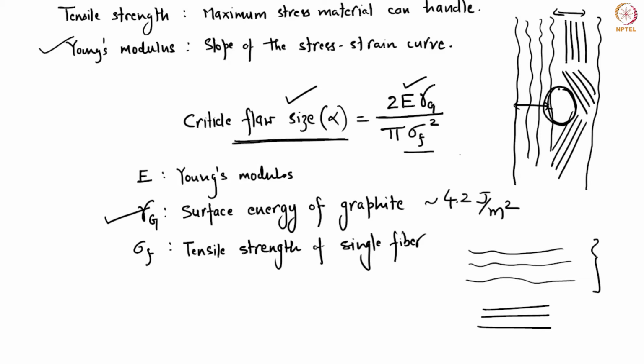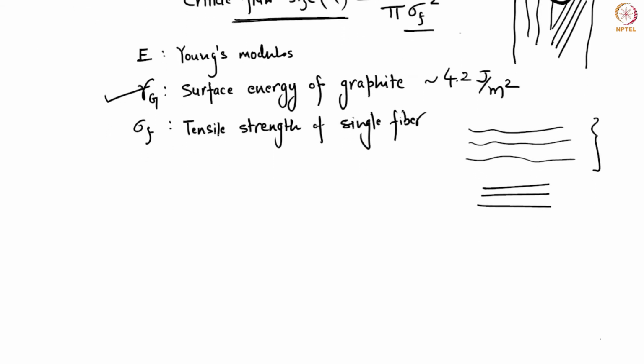Again, if the fiber is very thin, there is a high probability that some of these flaws will anneal out. Also, in the case of thicker fibers, some of them will anneal out, but not all of them. Some may remain trapped, and these are then your weak points in your fiber. That's where your fiber will break. Okay, so this is just to tell you that just increasing the carbonization temperature is not enough.